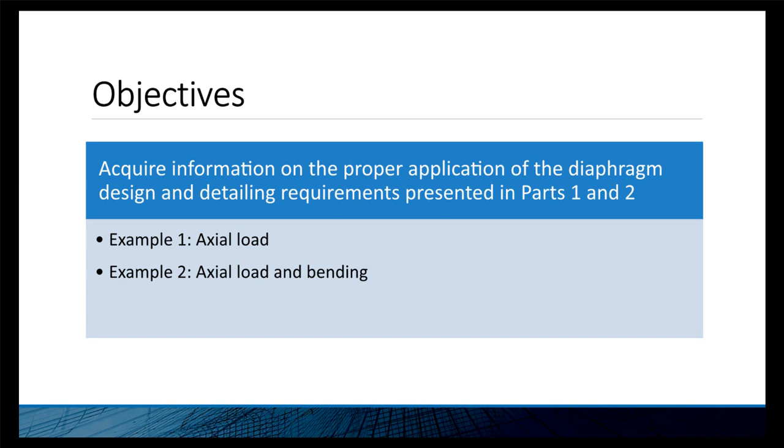In cases where we have shear and it's not covered explicitly in ACI 318, we're going to go back to what's in the CRSI design guide for pile caps, because really there's nothing else out there that fills the gap for us to design and detail the pile caps by.